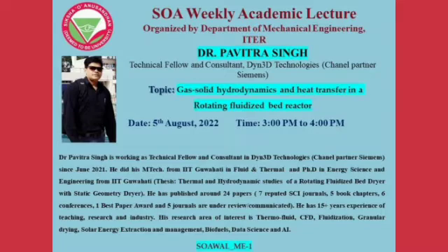So actually this is a rotating fluid bed dryer I have developed in my lab at IIT Guwahati. This is the electric motor, this is the air blower, this is the coupling, this is the air bypass valve, this is the air control valve, this is the orifice, and this is the manometer, and this is the air heating device, and this is the air distribution chamber, and these are multiple air inlets, and this is the main vortex reactor.